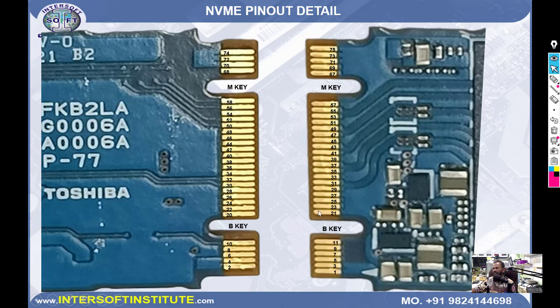And you can check here, some are power pins, the back side has power pins, here are ground pins. All these pins are important. To identify whether it is a firmware issue, software issue or hardware issue, we have to find the pin values, which we will see later in the PCB related part. Here are the Rx/Tx values. These 6 pins are the Rx/Tx. Here mainly power related issues are found, ground and VCC.